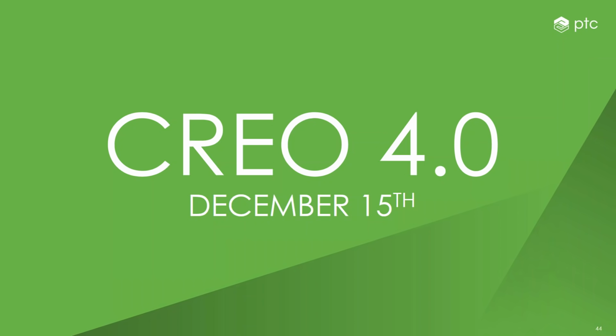The 32 character file name limit. Has that changed? Okay. Overall, that hasn't been addressed yet in Creo 4. We've done some work in certain areas to address it. So it's addressed regarding our Unite capability, for example, bringing data in from other systems that have longer file names. But for generally creating parts, you still have that restriction, as well as the restriction of special characters, so spaces and things like that can't be put in. It is something that we are looking to do. We haven't quite got there yet.